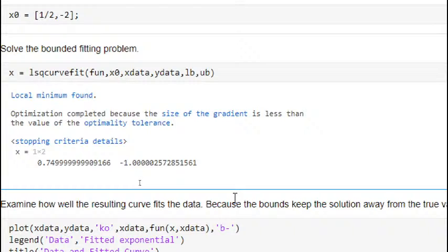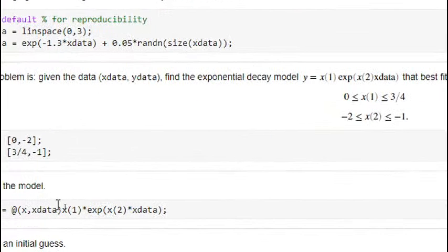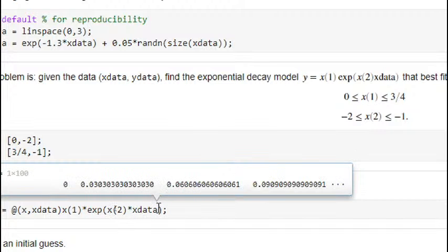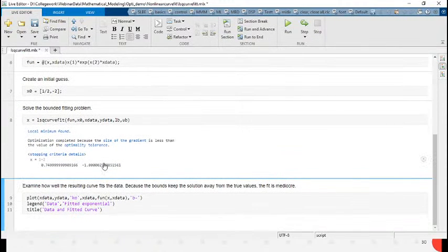So one thing you have to remember, you will have parameters like x y z, or p q r s, something like that. So you have to write them in the form x1, x2: x will become x1, y will be x2, and z will become x3. So you have to write your equation in MATLAB like this. Okay, and this is my objective function here, I mean optimize parameter value of x1 and x2.